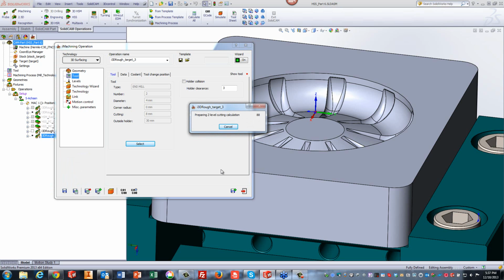Now this time it's going to go into areas where the previous tool cannot go, such as these areas down over there. It was not able to go into there, so it'll machine that as well, plus give it a little smaller steps so we'll be ready for the finished cut over here.